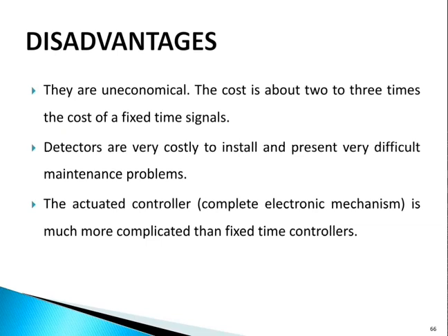see its disadvantages. They are uneconomical. The cost is about 2 to 3 times the cost of a fixed time signals. Detectors are very costly to install and present very difficult maintenance problems. The actuated controller, or say complete electronic mechanism, is much more complicated than fixed time controllers.